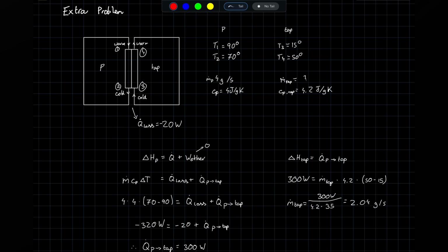And if these two things are mechanically separated, so if there's no electrical circuits going between the two, or shafts with pedals or gears or whatever, if it's just two passive elements, basically two metal blocks touching each other essentially, or two pipes, your enthalpy will only be a heat flow. And that makes things a lot easier, because as long as you have all the data for one subsystem, you can figure out your second subsystem.